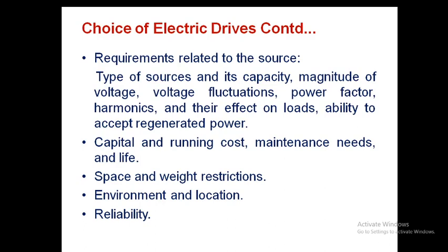And the reliability. Based on the reliability, we can choose one of the drives. The squirrel cage induction motor is more reliable, even though it has some drawbacks. If that application requires more reliability, we can choose that type of drive.